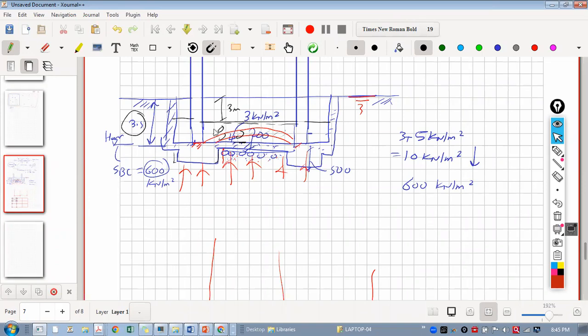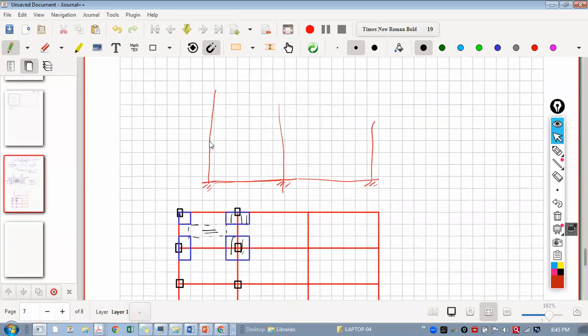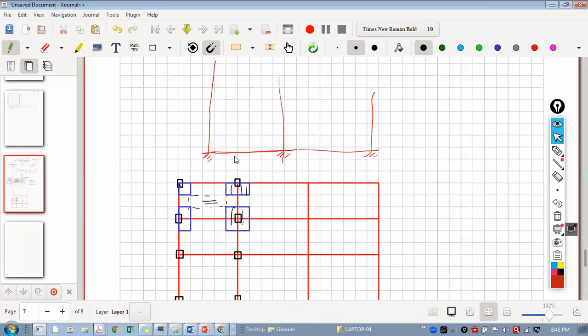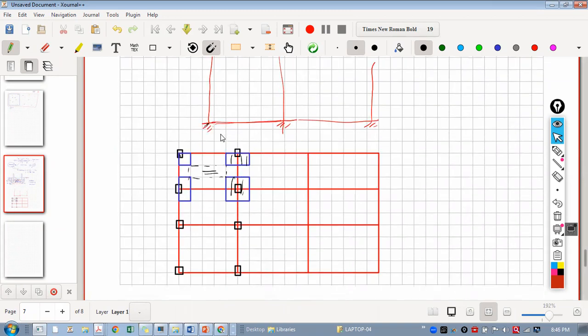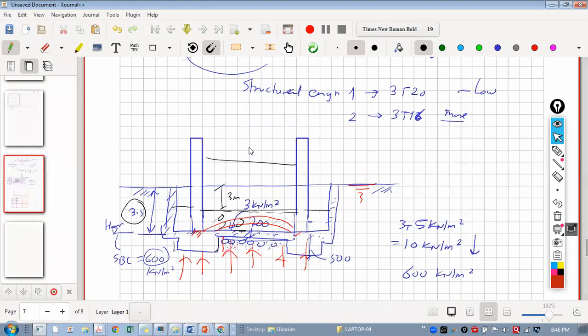Whatever you are saying is generally applicable for water tanks, because a water tank may float, because there is no footing like this, which is sometimes embedded in the rock. If the footing is in the rock, then this will anchor. So it will have a fixed support. Such kind of fixed support will be there. And this column will not go above, because if it is a building, there is a building above. That means definitely the building cannot lift, right? Only this slab will lift.